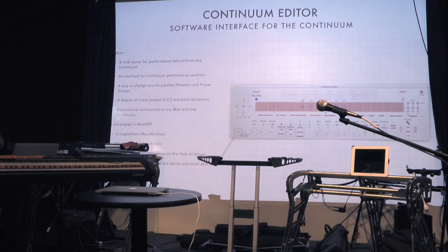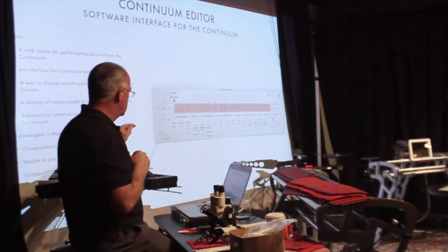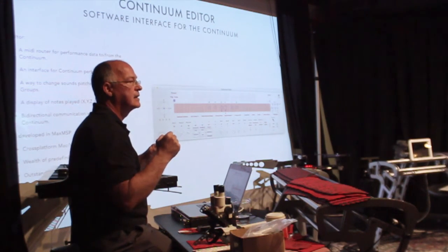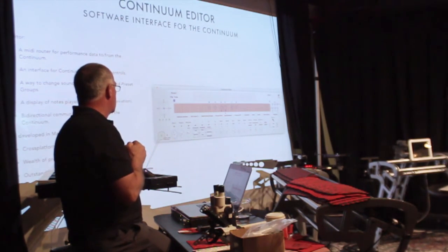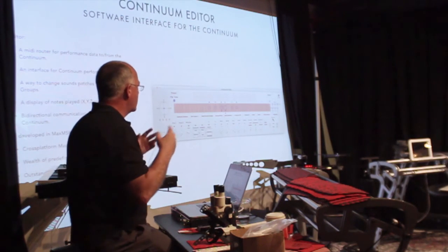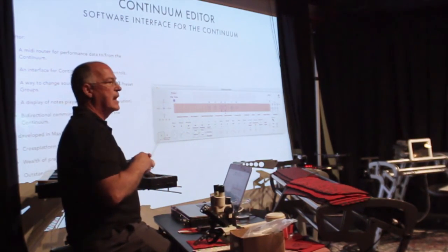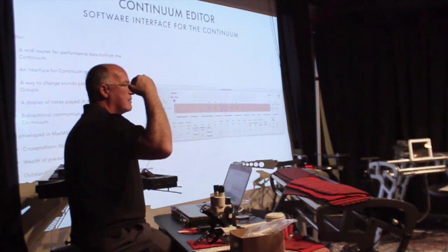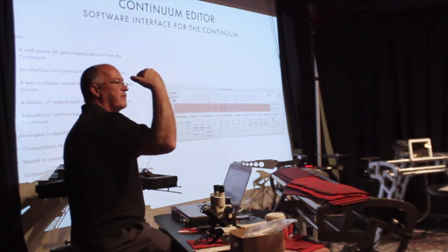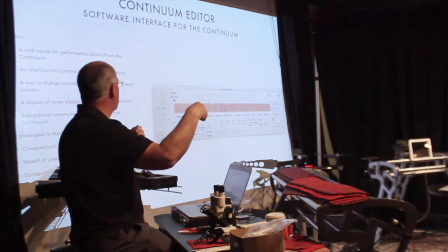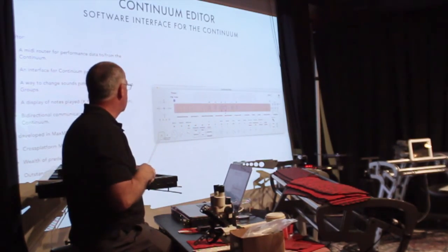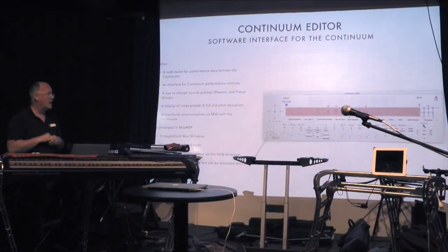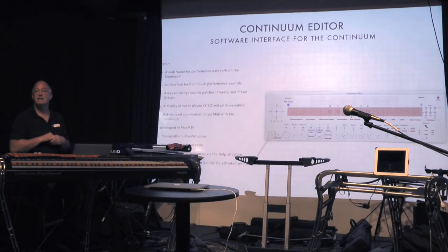And so this is whenever you open that up, that overload protector automatically comes on. We designed it this way because if you're in a performance mode and you have a sound up there, you can actually have a transient that is so loud it's going to go through the full range. It's going to go past 0 in the D to A, but musically it doesn't matter. You don't really hear it, it's so brief.